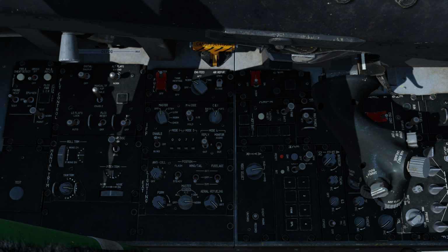When airborne, the pitot, fuselage air data, AOA, and total temperature probe heaters are on, regardless of switch position. Probe heat is in the off position.